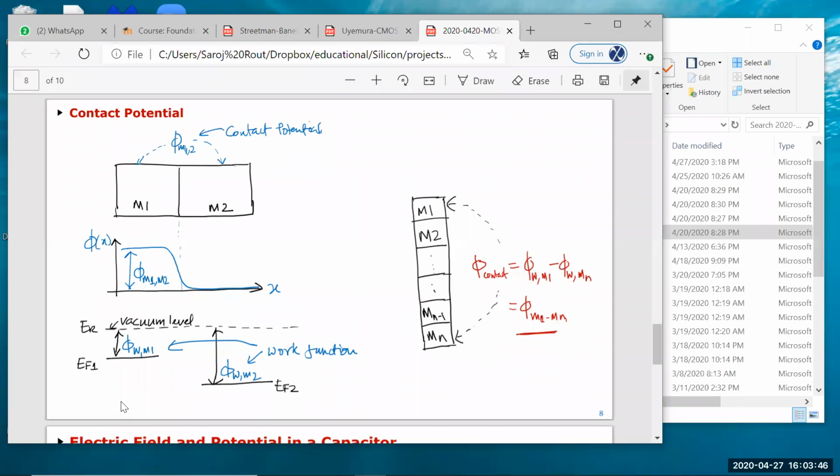For example, when you have the gate as a metal and the substrate as a P minus, you always have to remember that you have to apply a negative voltage to make the band flat. Once you know that, then if I make one side N type, you know that you have to reverse that. Or if I make one side poly plus, one side negative, that's because the Fermis have reversed direction, then you have to reverse the potential and so on.